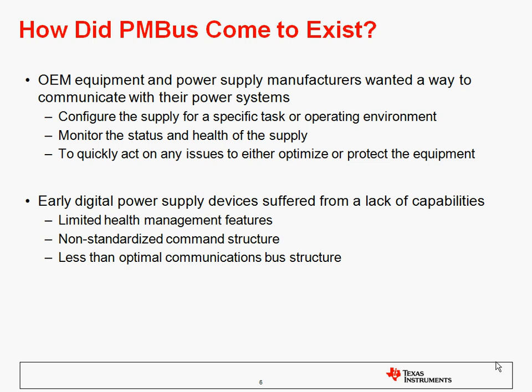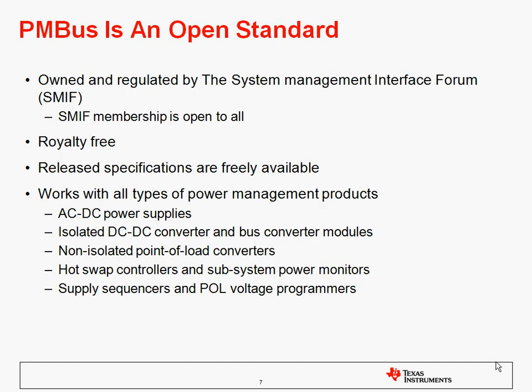And in the early days, digital power supplies suffered from a lack of features or capabilities. So they really had limited health management. It was a non-standardized command structure, so every time you tried to add a new device, you had to rewrite the code. And it was a less than optimal communications bus structure. So one of the things that PMBus does is bring an open standard to bear on the market.